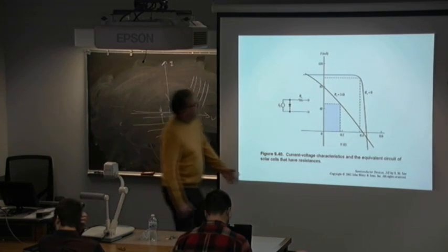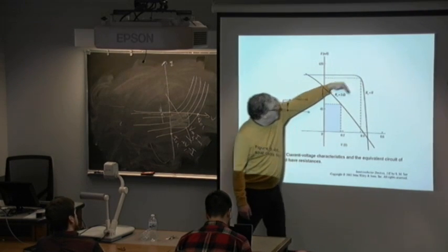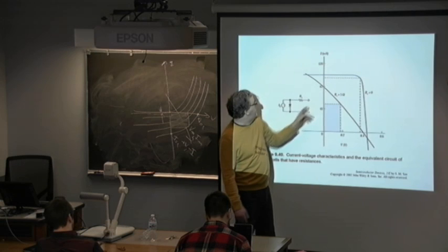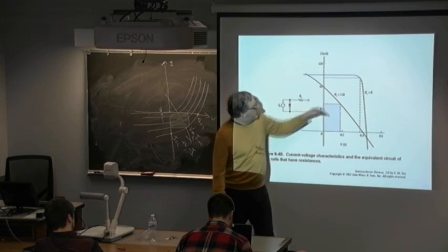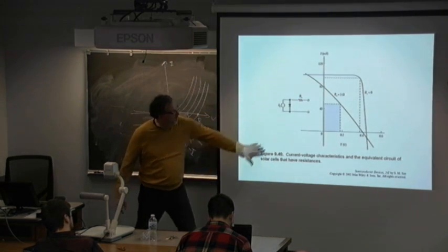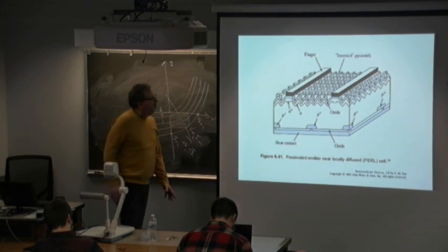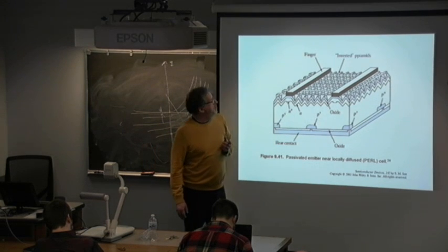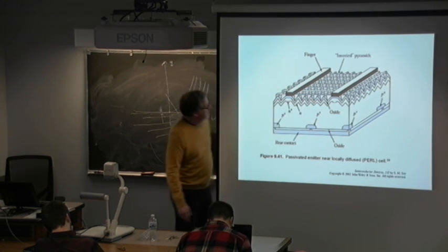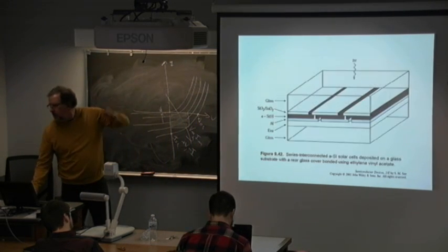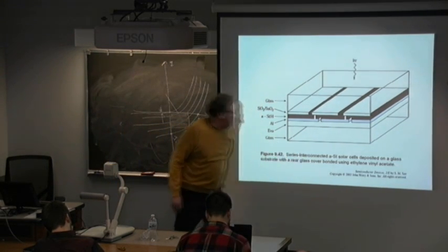As a solar cell is either made badly or gets old, it will walk away from this ideal condition. It'll start to get a series resistance, but also you can get a shunt resistance down here, a shunt current, and either way it's attenuating. So therefore you're losing power in that condition. So you want to get as many electron-hole pairs created as possible. You want every photon that comes in to create one, and so you want the light to ricochet around. The texturing allows it to ricochet around. Or you're using mirrors and stuff, perhaps.